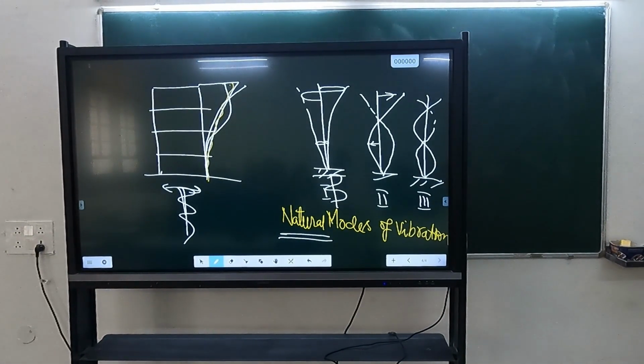As the layers have different stiffness because of the different value of G, because of the different shear wave velocity Vs, that is square root G by rho. In the same way, our stories, which you can think as layers, are also having different stiffness. So you can consider the behavior of the building very similar to that of a soil column.